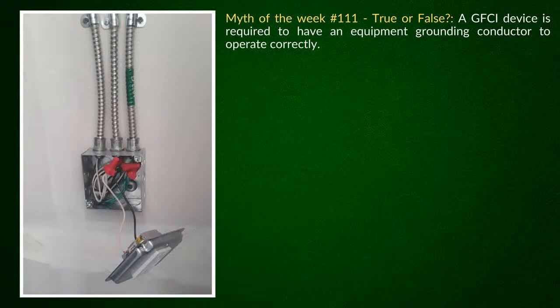But this week, the myth is false, 100% busted. A GFCI device works perfectly fine without an equipment ground.